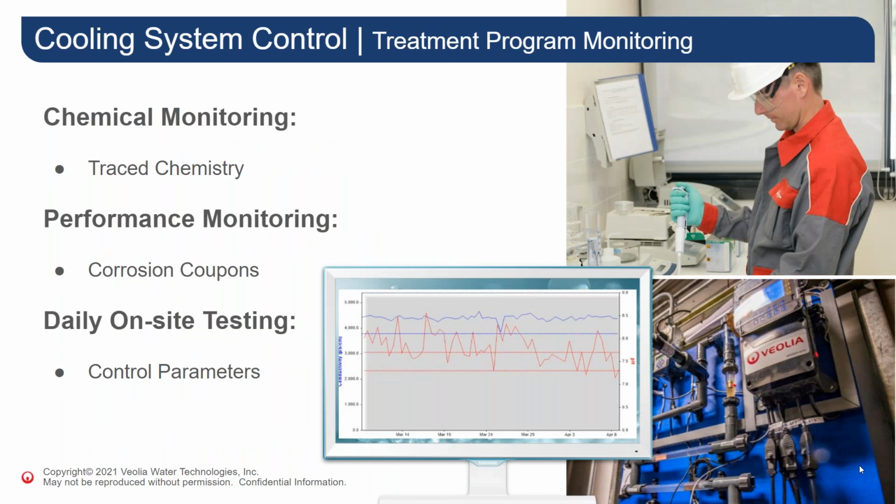Once a chemical treatment program has been engineered and implemented, keeping it running smoothly and correctly is extremely important. All treated systems should be tested periodically, typically at least once each day, probably more often for larger or more critical systems. Automation of a treatment program is relatively inexpensive versus additional headcount and is quite reliable.